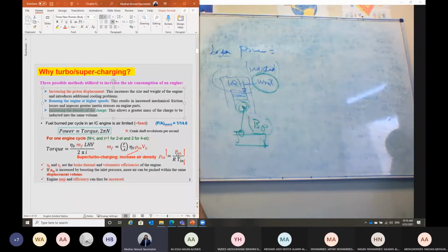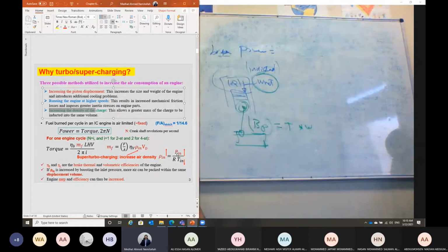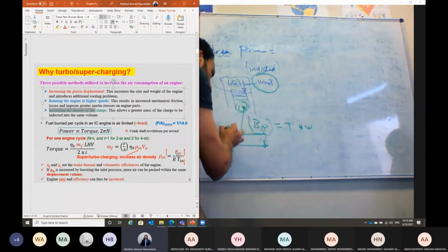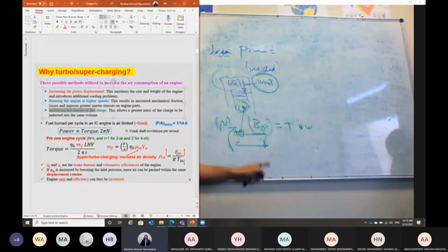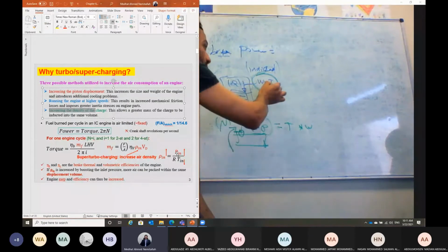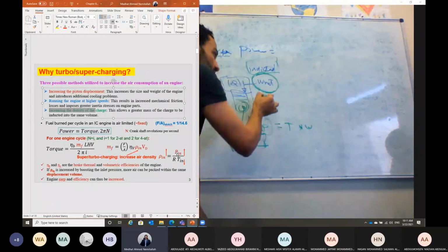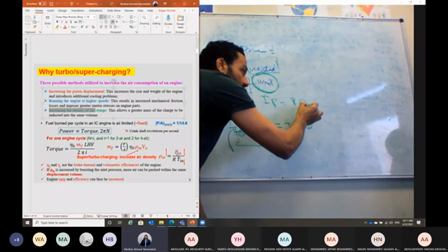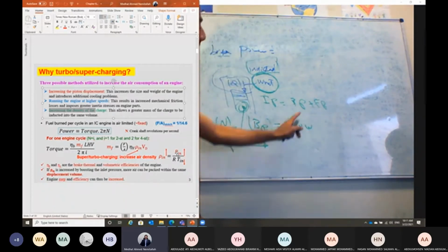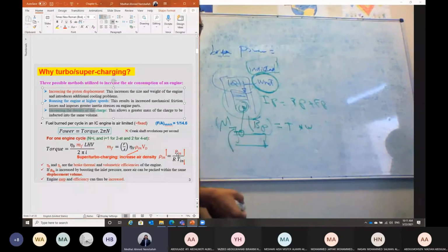the brake power. So the brake power is the crankshaft power, which is equal to the torque multiplied by the omega of this crankshaft. This crankshaft is rotating at a given RPM, and the power on this crankshaft is the final power. Brake power is the final power in the crankshaft, equal to torque multiplied by omega. But the net work that we have calculated based on the engine cycle analysis, we call the indicated power. The indicated power is equal to the brake power plus the friction loss power, the loss power due to friction, due to the movement of the piston, and due to